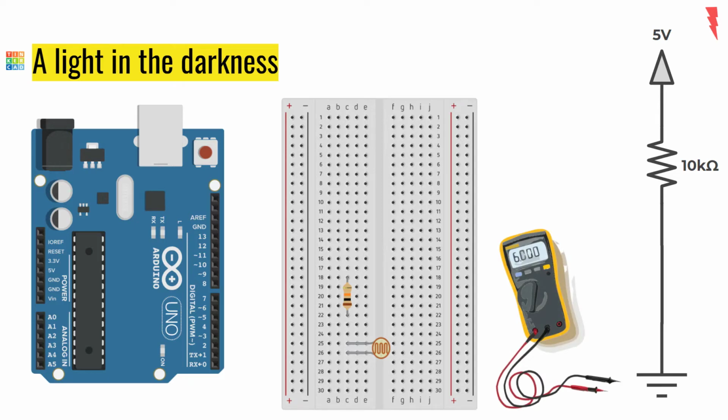Also, I'd like to introduce a multimeter to our arsenal of tools. We'll be using it to check voltage values. If you put both probes at the same point on any circuit, it'll read 0. The voltmeter tells you a difference in voltage between the two probes. If you take the multimeter and probe opposite sides of this resistor, then it will read 5 volts, because one probe is at 5 and the other is at 0, or ground, the difference of which is 5.